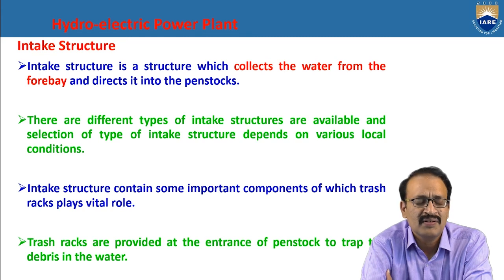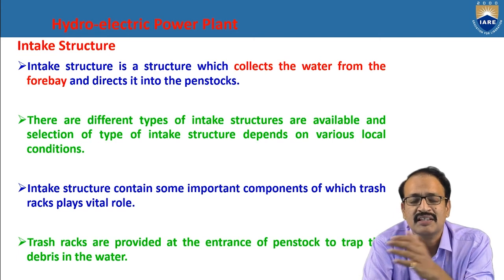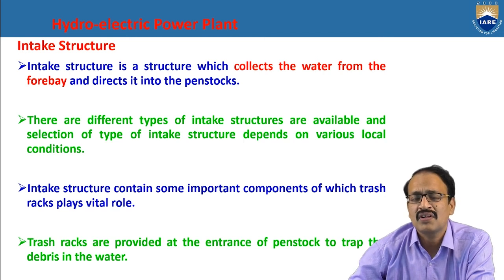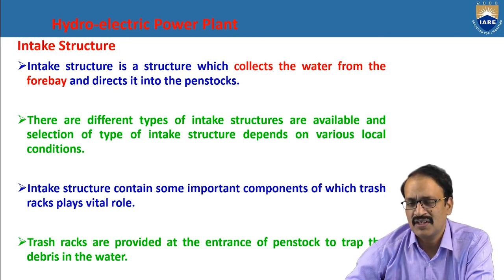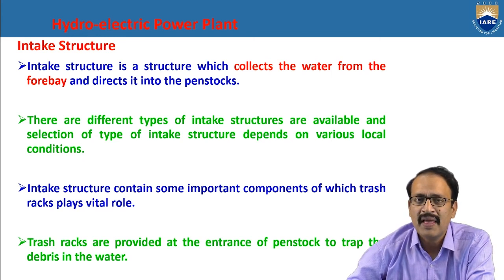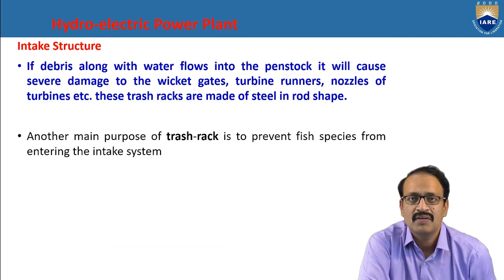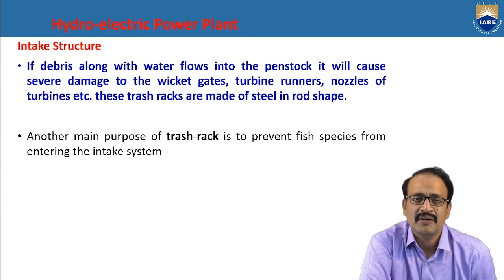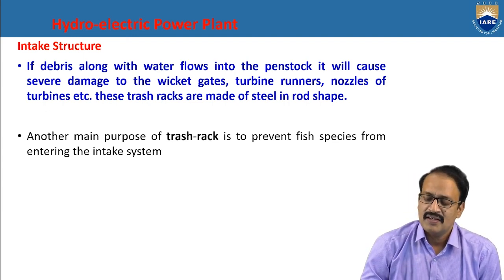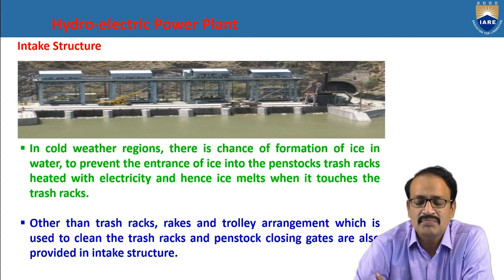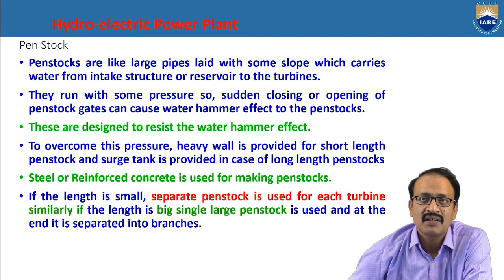Here in the intake there will be a trash rack, which diverts the debris, so it will not allow this waste and the fishes into the penstocks. Afterwards, after the intake, it enters into the penstock. This is about the intake.